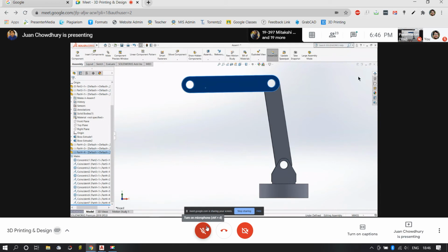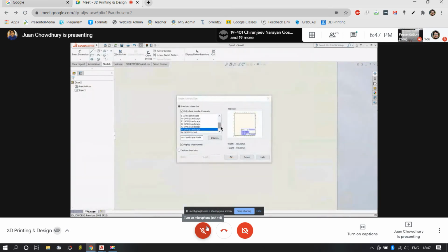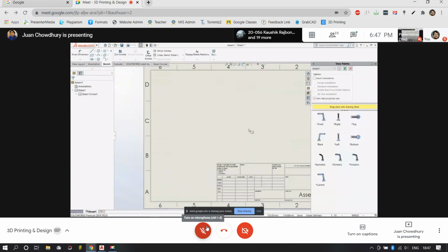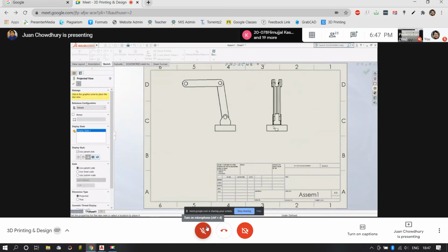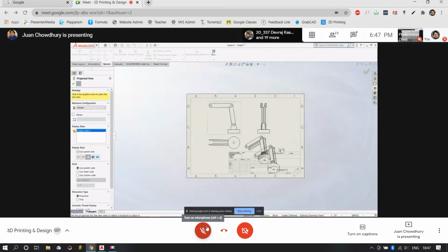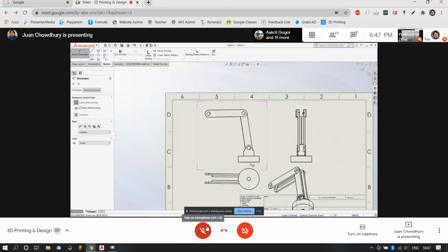Okay, let's check it out now. Make drawing from part assembly, select a paper. Okay, come up with front, side, isometric top, and isometric view. Okay, we can select a larger paper if we want. Now here we can go to sketch dimensions and you can put exactly what the dimensions are. Okay, you can see whatever we have put, all the diameters, holes, etc., everything is available.